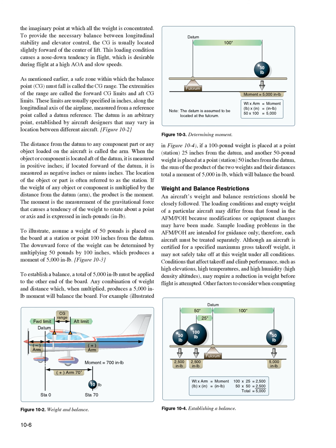The moment is the measurement of the gravitational force that causes a tendency of the weight to rotate about a point or axis, and is expressed in inch-pounds. To illustrate, assume a weight of 50 pounds is placed on the board at a station or point 100 inches from the datum. The downward force of the weight can be determined by multiplying 50 pounds by 100 inches, which produces a moment of 5,000 inch-pounds.